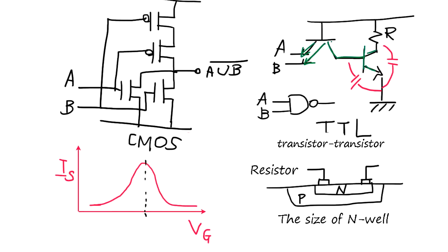So what happens is when one of them pulls down, then this transistor becomes on. So this voltage drops, then this becomes high because this current becomes zero. That dictates this voltage, right? So it's an AND, opposite polarity. One of them goes low, then it becomes high.